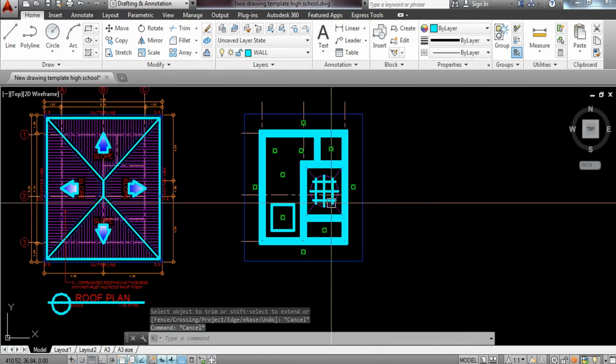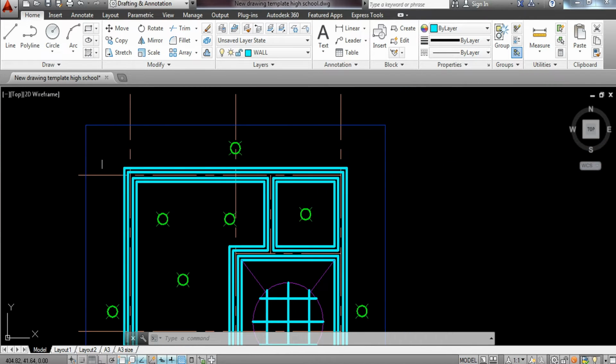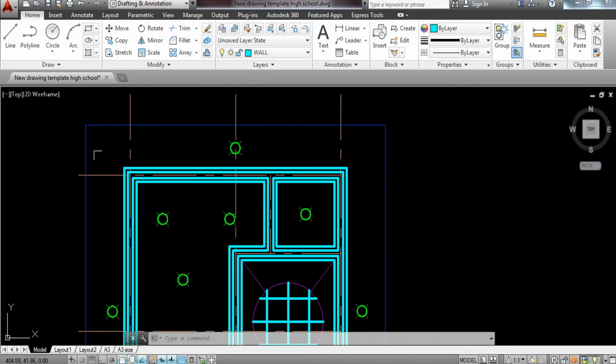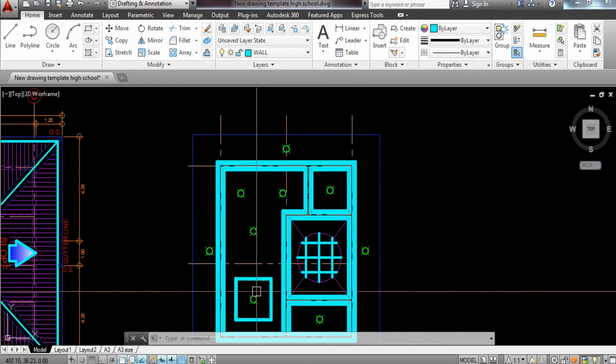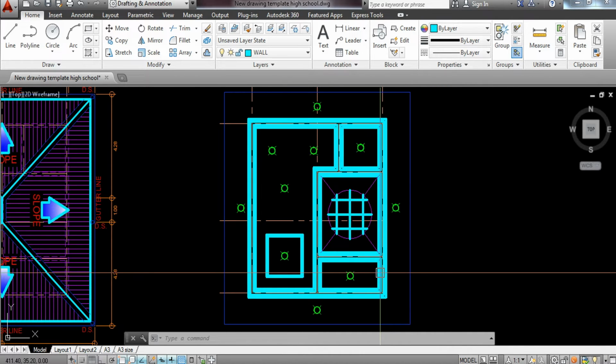Now, not to forget, the position of the soffit. Soffits are always placed outside the eave line, outside the roofing, at the bottom, somewhere here. This is used to release ventilation. It serves as ventilation to allow the heat and cold inside the roofing and in between roofing and ceiling to get out, so there is a passage for the heat and cold.